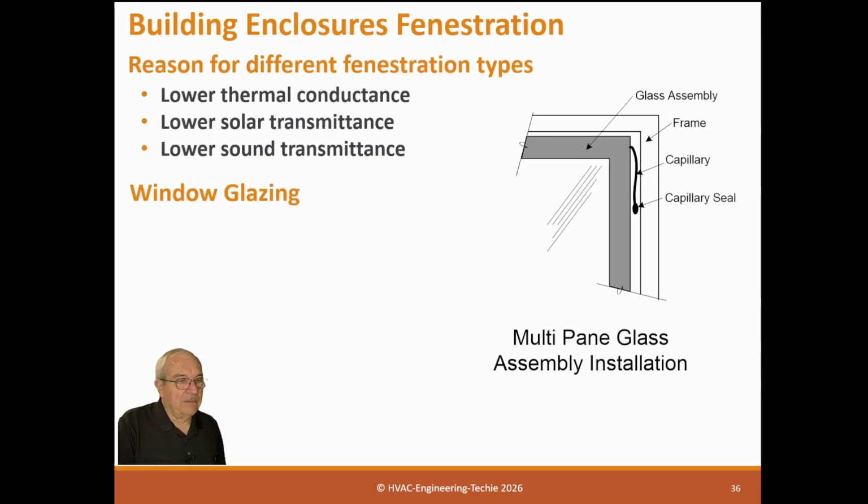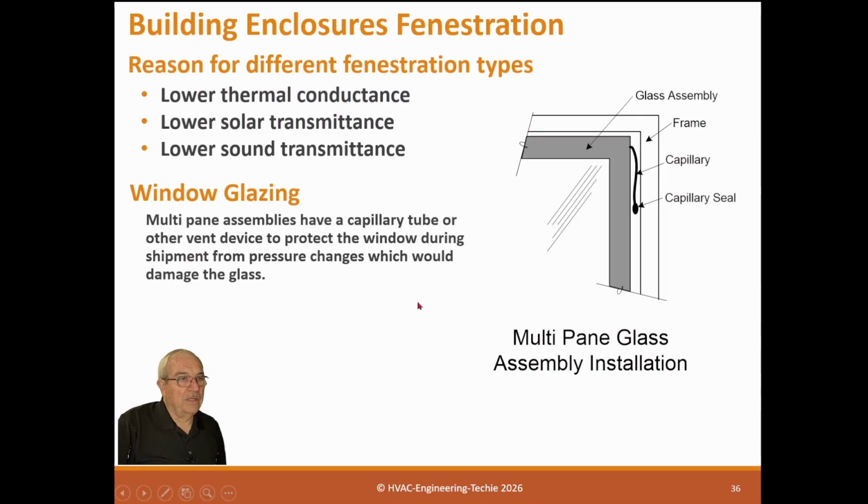Now, one thing about the rule here is that in design, you always try to not have a sunlit window, because a sunlit window transmits a lot of energy. When you're doing a heat gain, you've got a difference of 40 degrees, and you've got a wall factor of 0.15. That all looks good. But you take and sunlit that wall, now instead of using 40, you've got 158. So it's 4 or 5 times more temperature transmittance than if it's not. So we try to do shading such that the windows are not sunlit, or if they are, for a very short period of time.